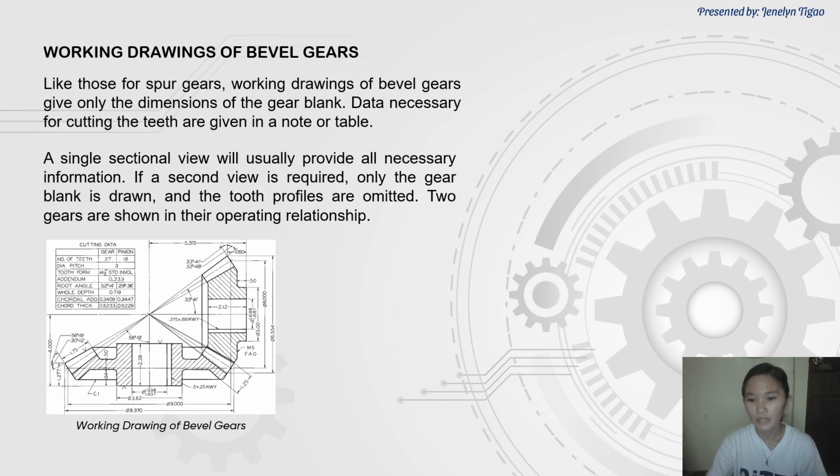So, what is a bevel gear? A bevel gear is a toothed rotating machine element used to transfer mechanical energy or shaft power between shafts that are intersecting, either perpendicular or at an angle. This results in a change in the axis of rotation of the shaft power. Aside from this function, bevel gears can also increase or decrease torque while producing the opposite effect on the angular speed.